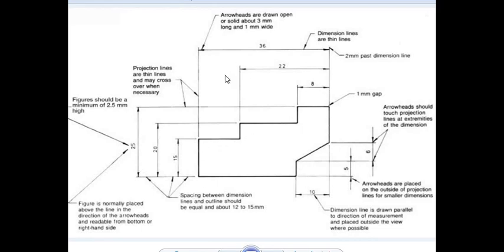You can see that in this particular figure. And keep this point very much in mind, because many students when drawing will draw the dimension line and the extension line and all these things with thick lines, which will spoil the details of the main drawing. So this is about the dimensioning of the features. There are certain other things that I will discuss now. So hopefully everybody understood these things.